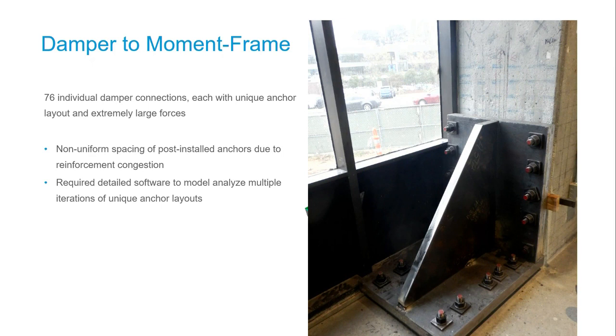So we, again, went to the CBFEM software and utilized the complete custom baseplate configuration for that. And we were able to model each of our different configurations, see exactly what we needed to do. Do we need to thicken the baseplate in order to avoid prying in some of these cases? What are we really going to get out of these forces? And this again helped us efficiently design that whole system.